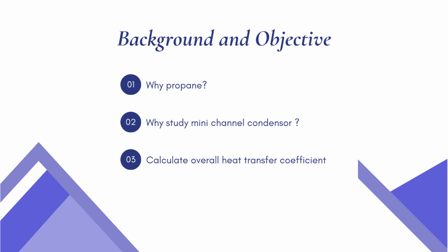In this project, propane is selected as the refrigerant due to its low global warming potential, excellent thermodynamic properties, and high latent heat of vaporization. It is also a natural refrigerant, making it an environmentally friendly alternative to synthetic refrigerants like R134A or R22.